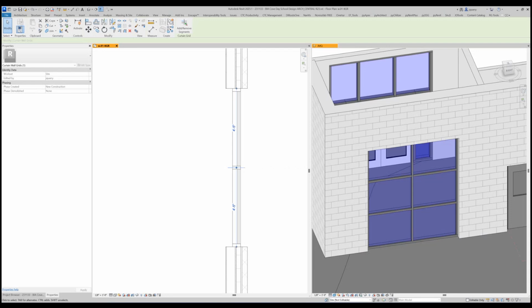So let's go ahead and use 1'4", for instance. The interesting thing is the dimensions that they did here are weird. That's not how I dimension them. We dimension mullion widths and not to the centers. That being said, let's figure out this 1'4" and 1/8. The good thing is because they gave us 1'4" to the center, we don't have to do any math. Because we know to the center of that mullion is 1'4", we know where that is.